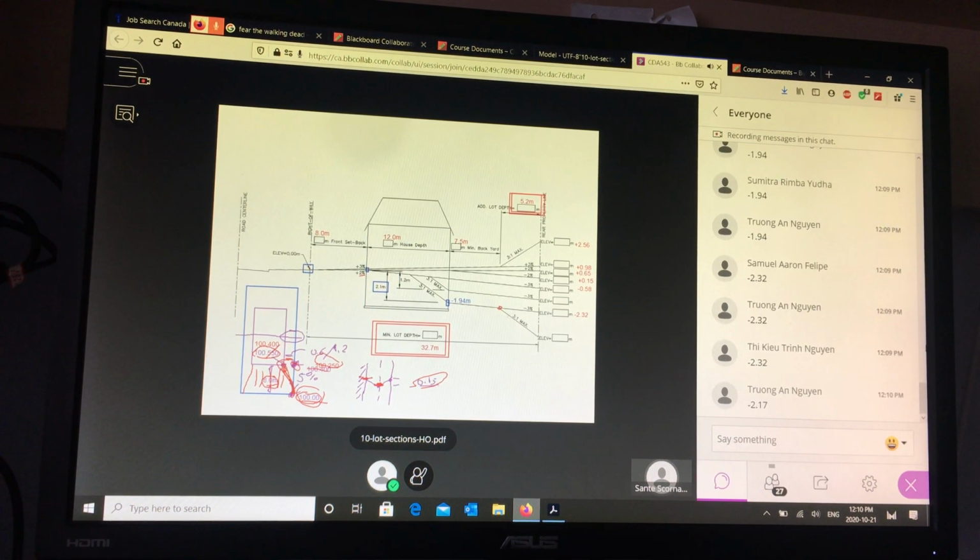Yep. So that elevation here is going to be negative 2.165. And then what would the elevation at the back of the lot be if we were going to maximize the 3-to-1 slope? You know, with the two decimal places. Negative 3.89, I get 3.89, that is correct.